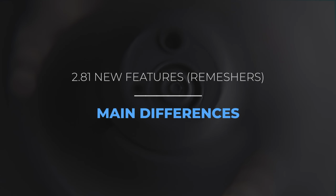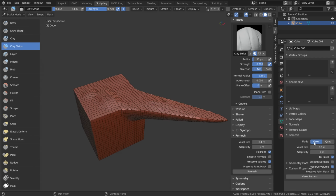There are a few other differences between the remeshers, so let's take a closer look, starting with the Voxel Options. Put simply, the Voxel option is a faster and more basic algorithm. Quadriflow takes longer and will try to respect the flow, the curvature of the mesh a little more. But let's put the Voxel remesher a little more under the microscope.